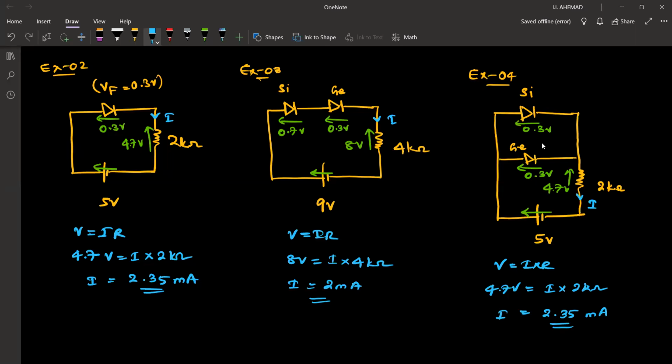Because we know in a diode, soon after it is forward biased, the current that can flow through it increases rapidly, right? The current increases rapidly. Just think of this path as resistance-less as soon as it is forward biased. So this is high resistance, this is low resistance. So the current will choose this path, and as it can flow through this, it doesn't even think of forward biasing this. Okay.